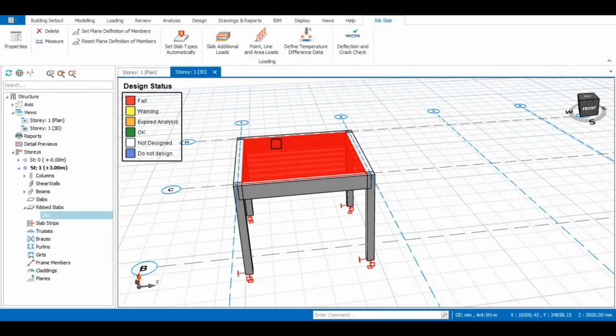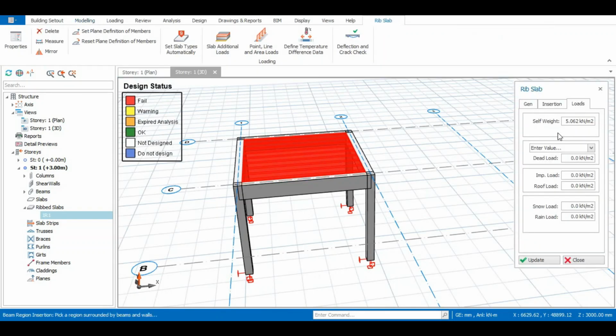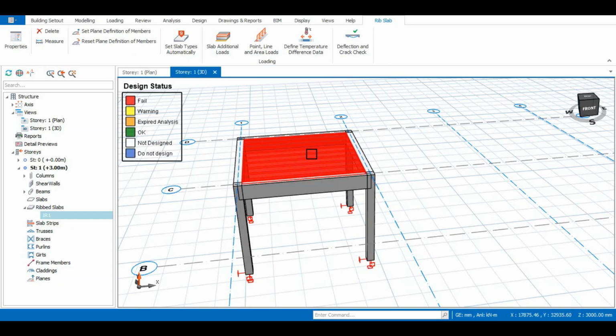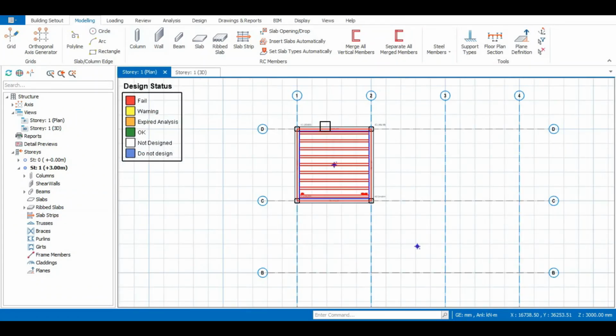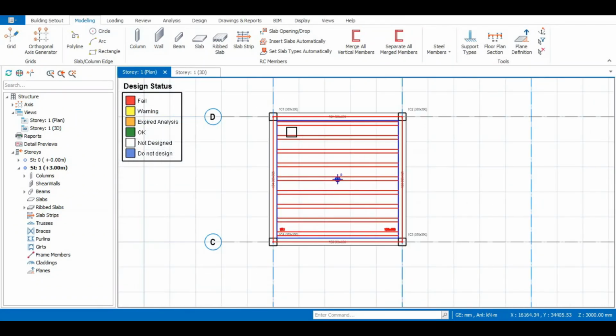You can also design the loads. So once they want it to be rooms, and you see that you have the soffit here, so you have the rooms, and you can have an imposed load to be, let's assume that imposed load is 2, and you can just update that and then close here. So what is left for us to do now is to finish modeling this. So we can go back to our story 1. What we need to do now is to go and do an analysis on the rib.